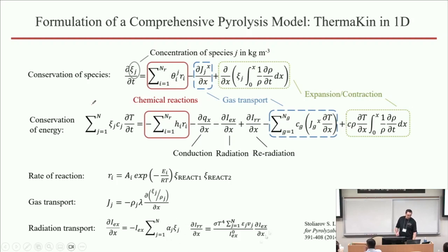And we have finally this radiation expression, and not going to detail of formulation, I want to point out that the reason it's formulated this way is to ensure that the very same solid elements that absorb radiation from outside also emit radiations in the same proportion. And that ensures that your problem is compliant with the second law of thermodynamics. In other words, you do not create any possibility that the temperature of the body that is being heated rises above the temperature of the body that is the heat source.